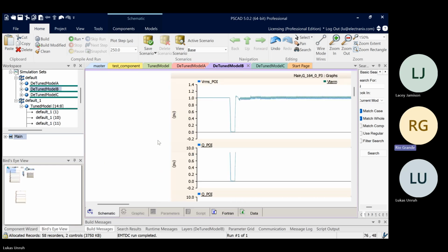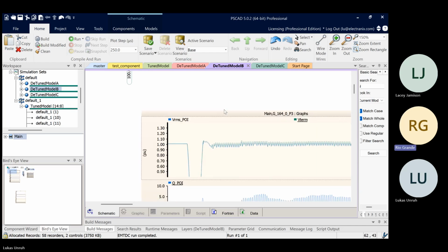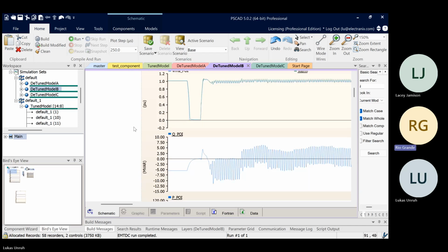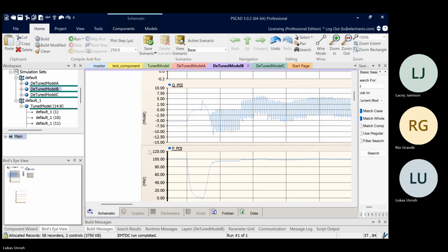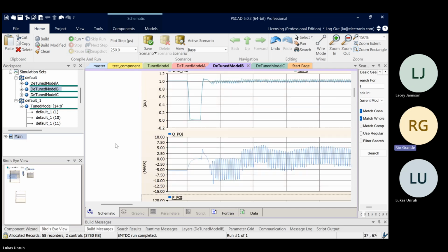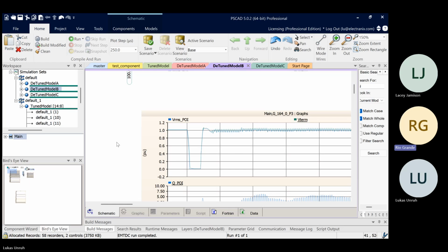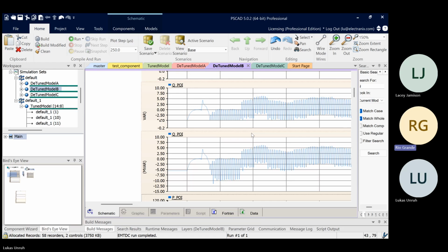Scenario B here. So again, I've detuned this controller in a different way. Let me put the time axis on here. Red, you can see each division is, now we're looking much closer. Each division is 250 milliseconds here. So this is a much higher frequency oscillation. Pretty heavily focused in reactive power here, but definitely visible in active as well.